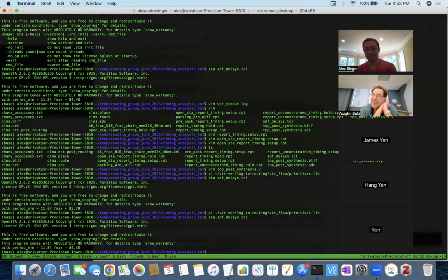I'm not sure. It'll be interesting to look into that because that could be another reason why you'd want to use a flow like this, because then VTR may not have this unate non-unate stuff, because maybe it's a bit too much work to do that during pack, place, and route. But OpenSTA, because we've already packed, placed, and routed the circuit, we can be a bit more accurate, I guess. It's also just work to code all this stuff.